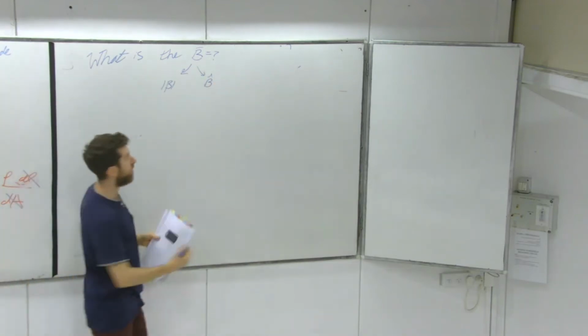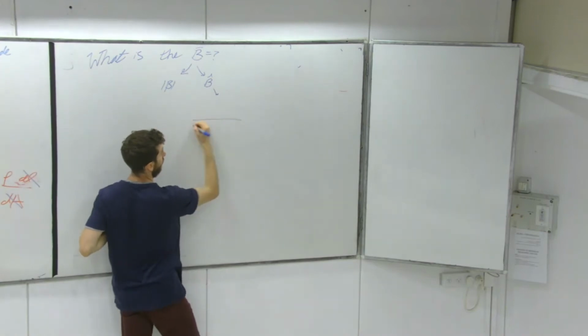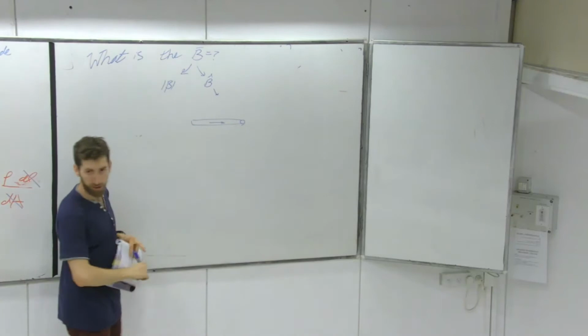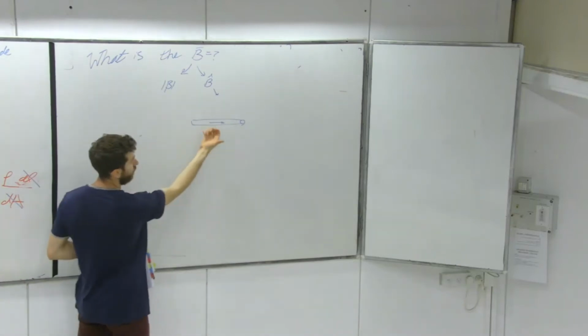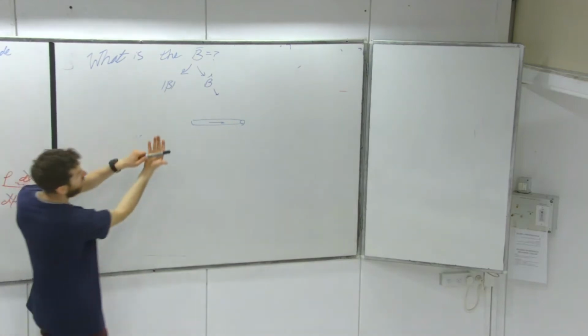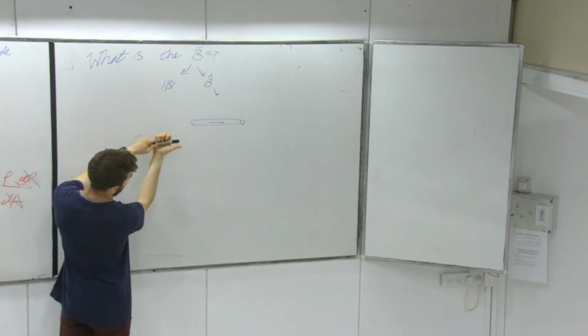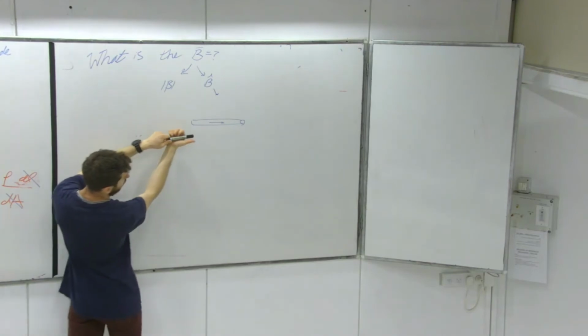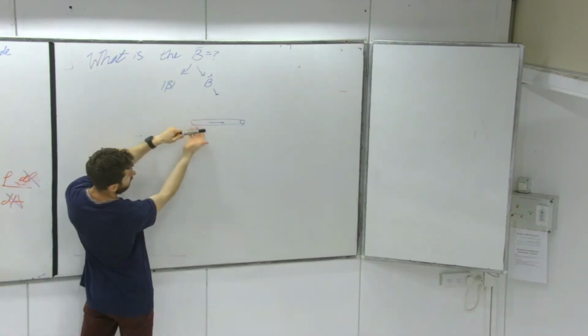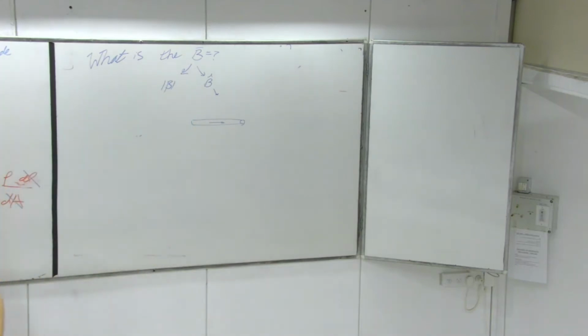So how can we deal with the direction? We said, look, you have the wire, got it. You have the current going in that direction. So if you grab this wire, for example, if this is my wire, and I grab it, I can see that the thumb is pointing in the direction of the current, and the fingers are going to curl in the direction of the magnetic field.